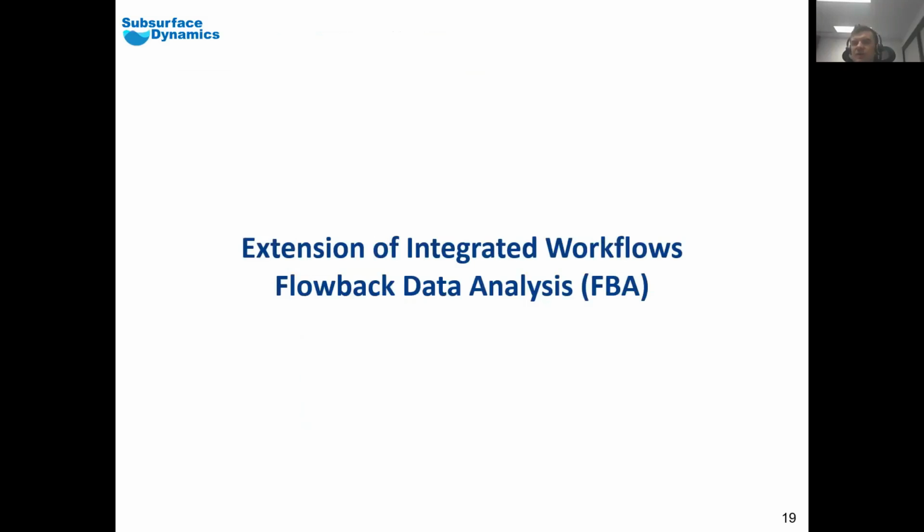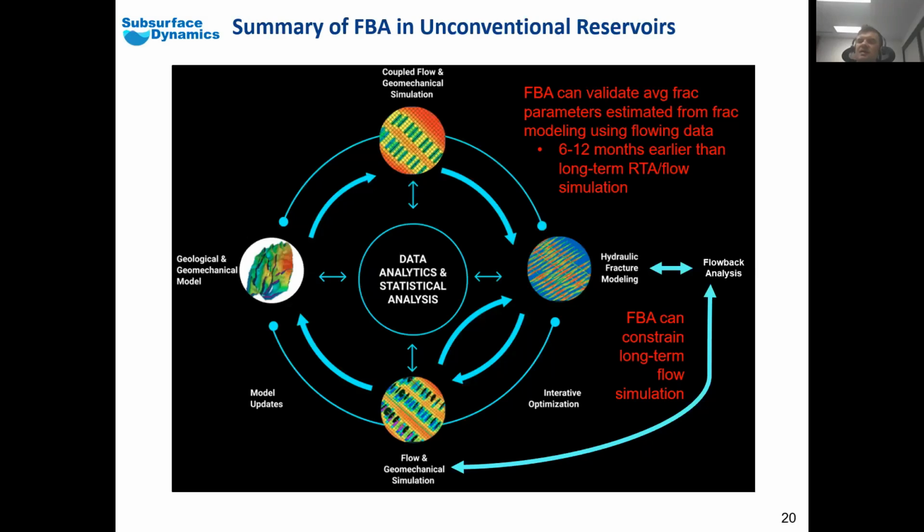The new piece of science that we recently introduced into the integrated workflows is quantitative flowback data analysis. It's similar to the RTA technique, used to analyze the flowback data, which is the completion fluid and completion water production after we pump our well and go into the cleanup flow, and derive the fracture properties.